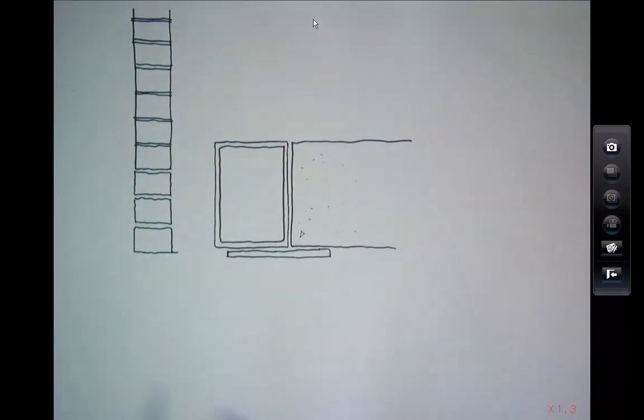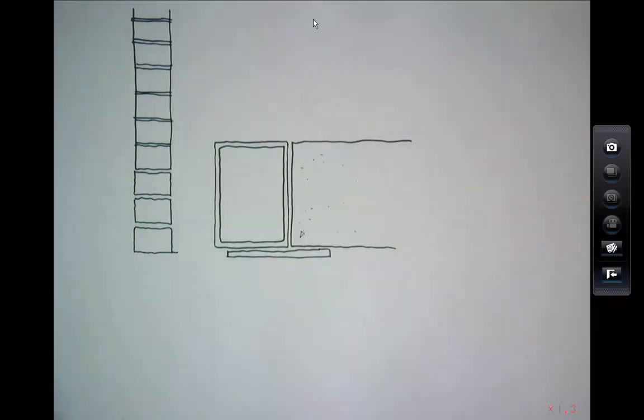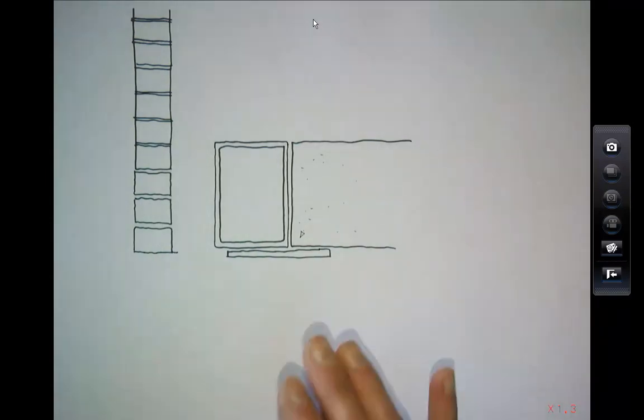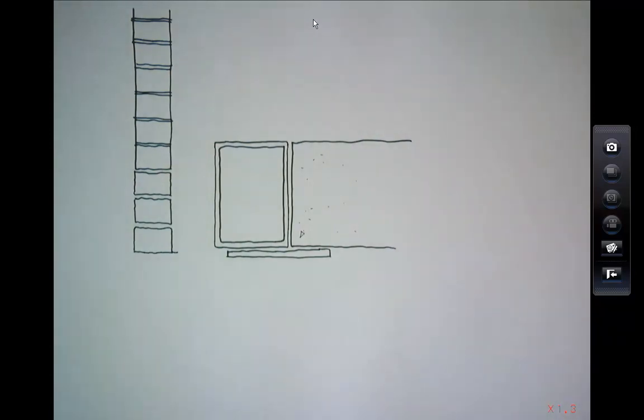If you think about it early on, you often find you can design a parapet in and it's absolutely fine. If you forget about it and you leave it to the end, then obviously it's too late to put a parapet on your amazing roof. So it's just one to bear in mind, because it becomes a real design consideration in practice. Okay, not so much in School of Architecture.